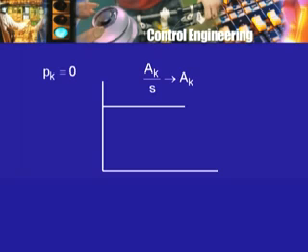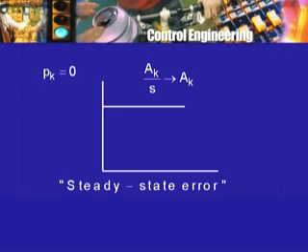But because it remains constant, it will keep on surviving as time increases. So it will contribute to the steady state, that is, it will remain even when 20 time constants have elapsed or 100 time constants have elapsed, it will remain there so long as the system is operating. So it contributes to the steady state, and we will see later on that this can contribute to the steady state error. That is, this kind of situation can, not necessarily always will, but can contribute to a steady state error.